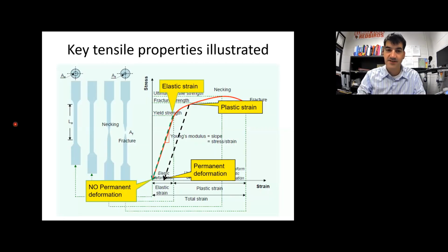So the way you would calculate the elastic modulus is by selecting 2 points on this linear region right here. Say a point down here towards the bottom of the linear elastic region and a point up here close to the yield stress. And then look at those 2 points and calculate the slope between them. Remember that slope is rise over run.